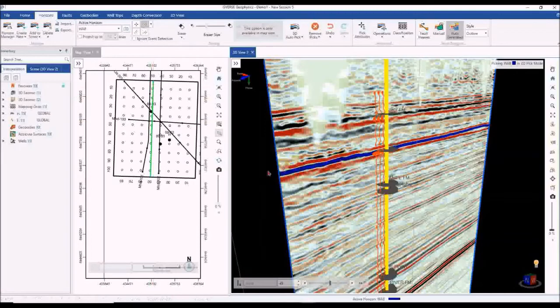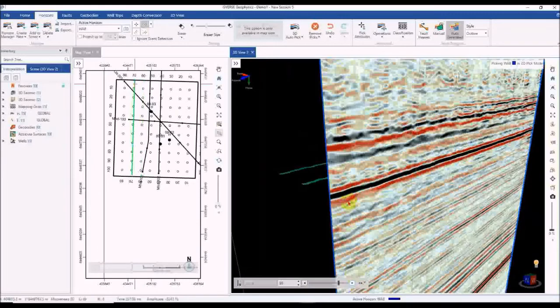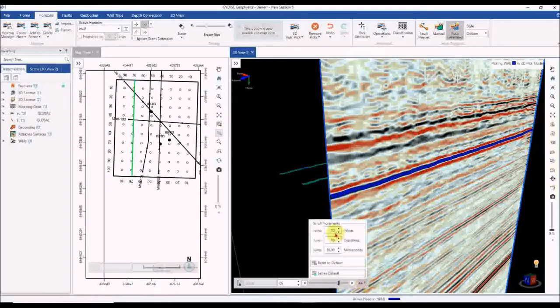What we have noticed is that it went along the cross line in this case to get the interpretation of this section. So what we could do is increment in one direction and then just click, and it's been set here to go every 10th. And a nice addition in 2019.3 is that we have the toolbar down here, and we could set right here the increments or jump, in this case, to a specific value that we want.